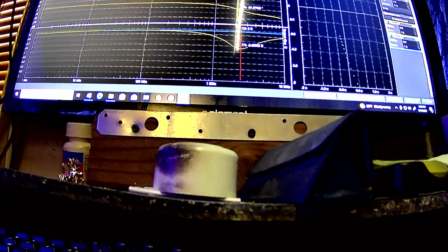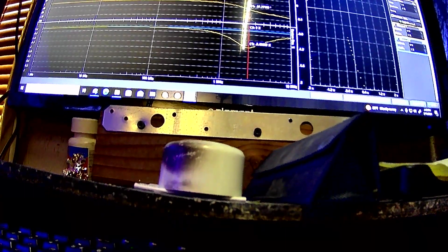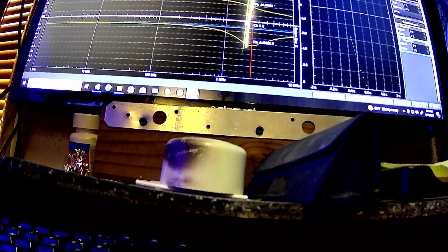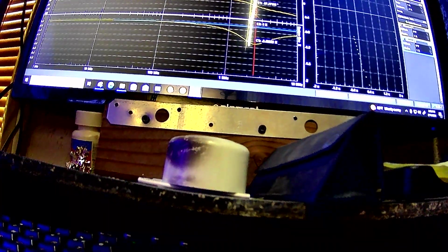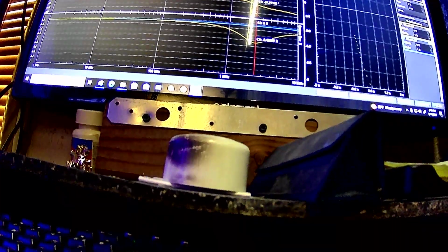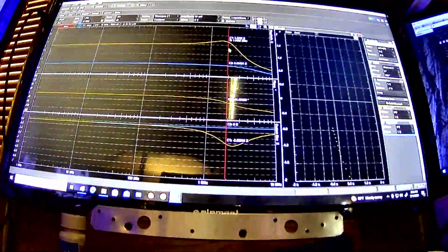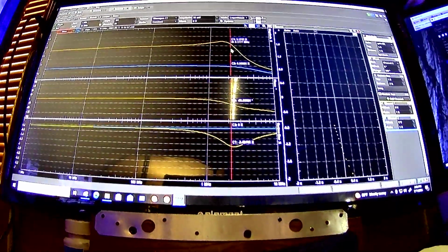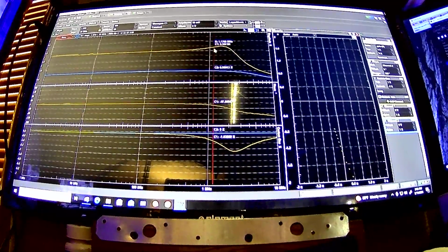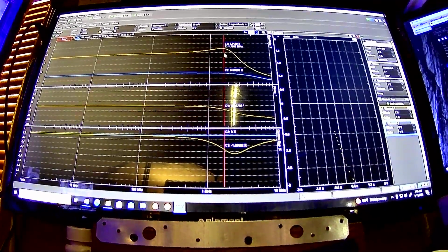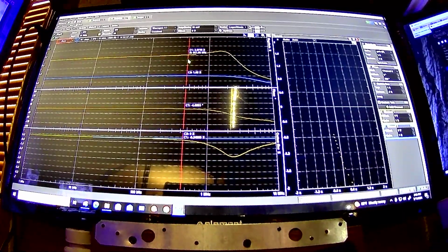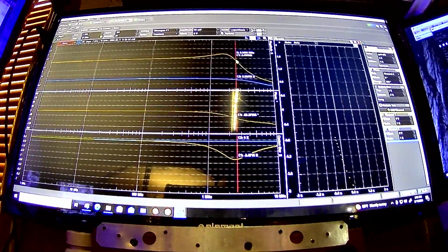But hold on, because like in the 5532, for example, I don't really see a graph that shows that. Again, this ON Semiconductor is the only decent data sheet I've found, and that's not really decent. It has just very minimal numbers of graphs. It doesn't show that, but as far as I can tell, all op amps do actually have a hump like that in it, at some frequency where they're starting to kind of run out of gas or whatever. Here this starts really early, but that's a sign of distortion.